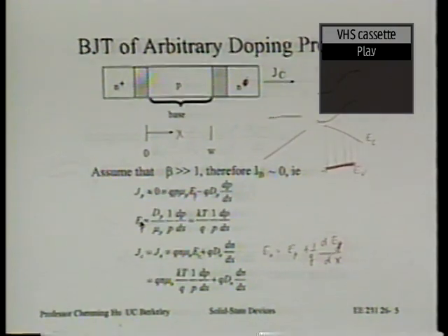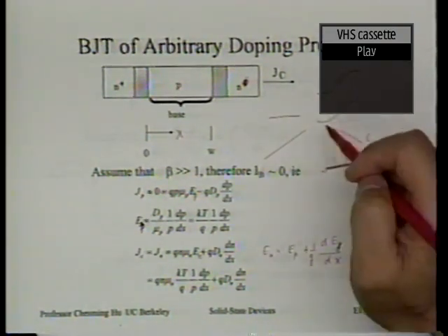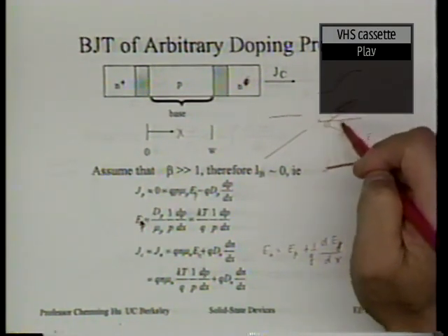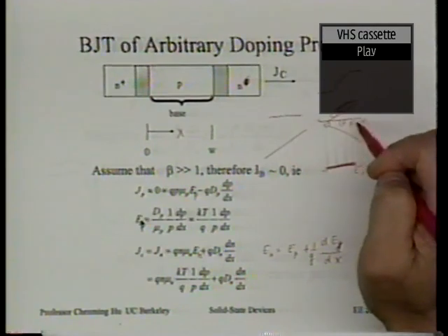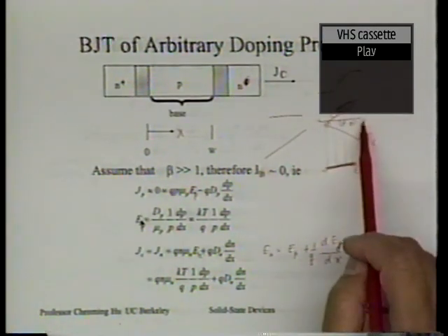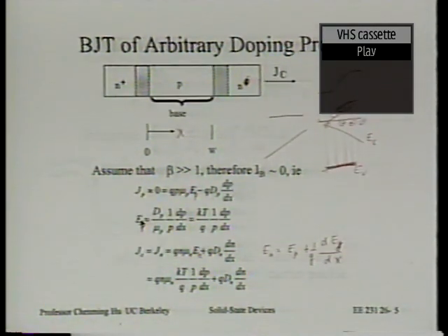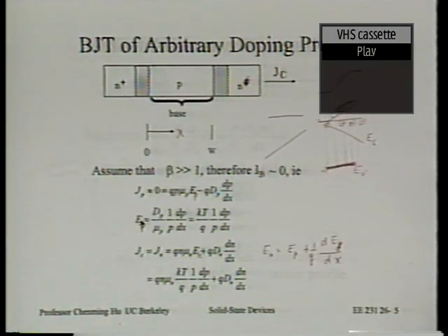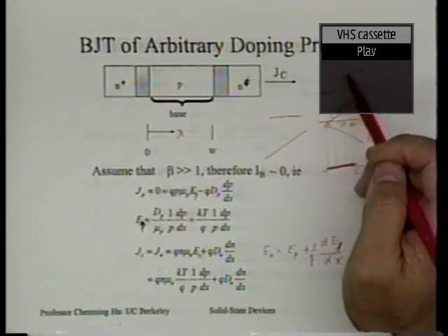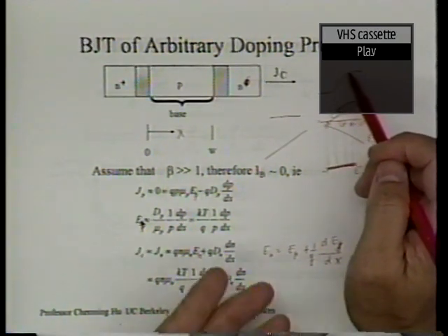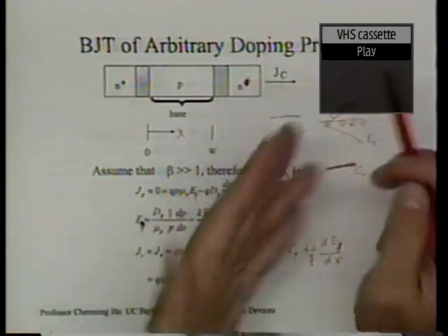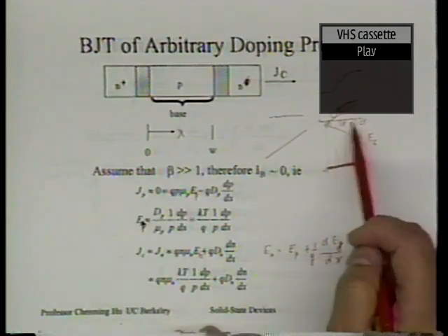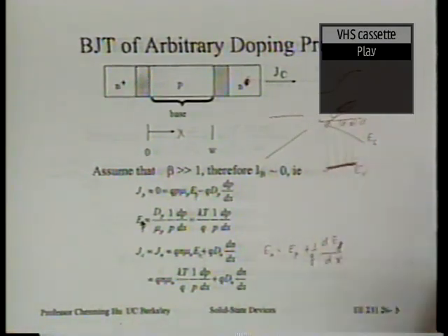Now, if we create a material situation by changing the band gap such that the potential for the holes is not changing, it's the same potential for the holes, just because band gap here is larger, band gap there is smaller. Certainly, the electrons will see a field. In other words, for example, this drift tendency must be balanced by a diffusion tendency. Otherwise, you have a net electron current flow. Here, you won't have that problem. You won't have a drift hole current flowing.